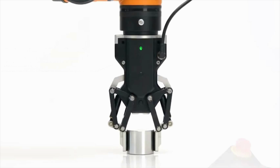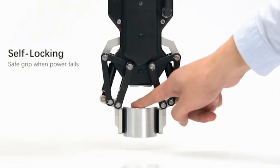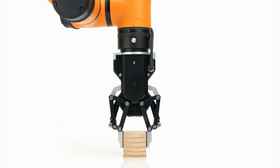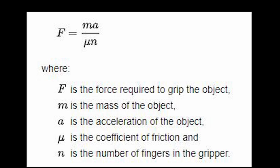The robotic gripper must withstand not only the weight of the object but also acceleration and the motion that is caused by frequent movement of the object. To find out the force required to grip the object, the following formula is used. F = ma/(qn), where F is the force required to grip the object, m is the mass of the object, a is the acceleration of the object, q is the coefficient of friction, n is the number of fingers in the gripper.